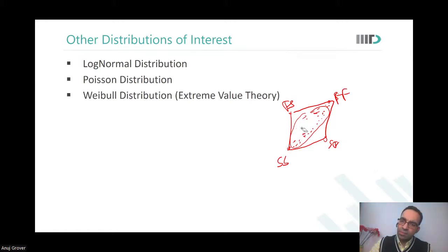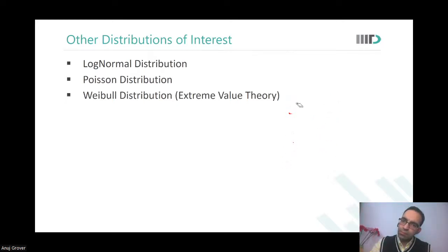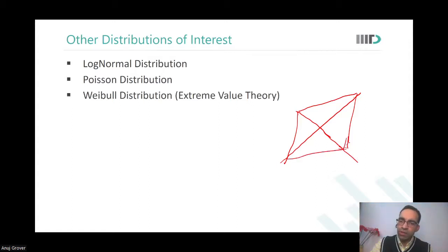So the actual question is, what exactly is the impact of CPK? What I see in CP is different, but when we model Monte Carlo, what does Monte Carlo have control over? Does it shift the mean also, or does it only consider the sigma variation? It changes from tool to tool, Raghav, and it also changes from fab to fab. Some fabs would say, I will model all the lots and all the variations in one simulation itself.